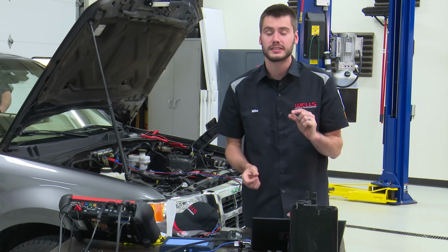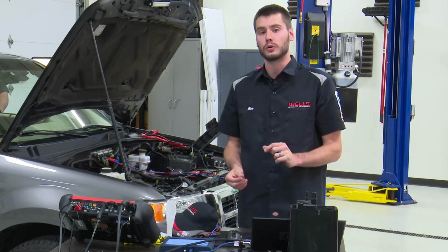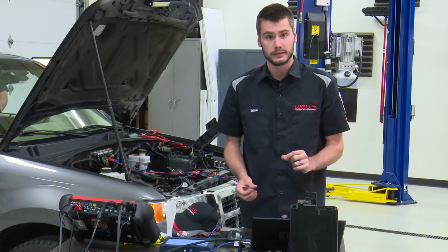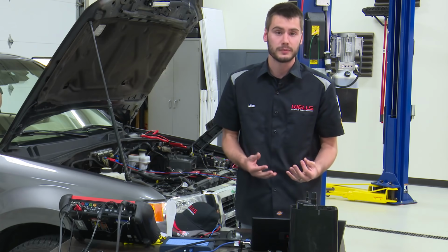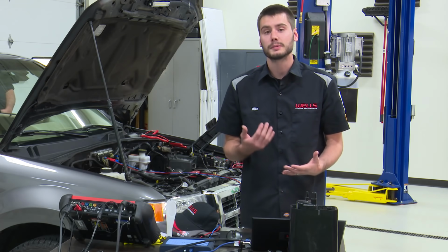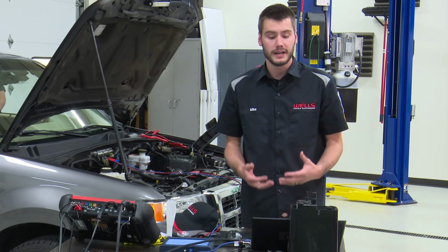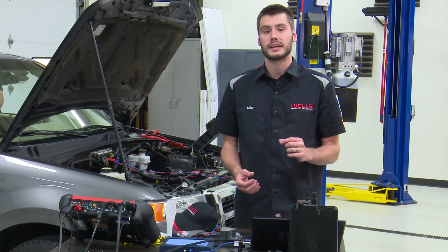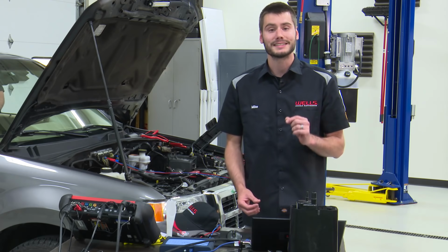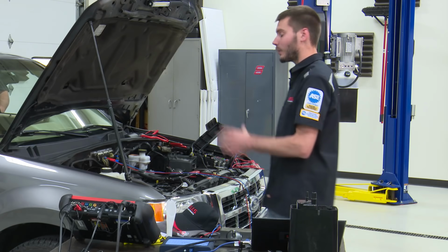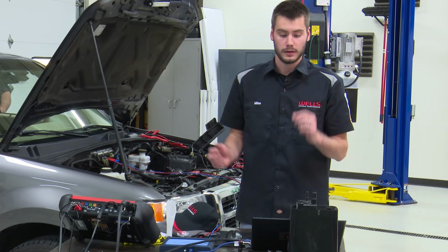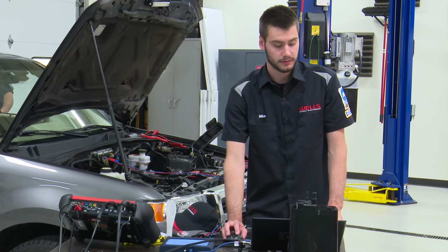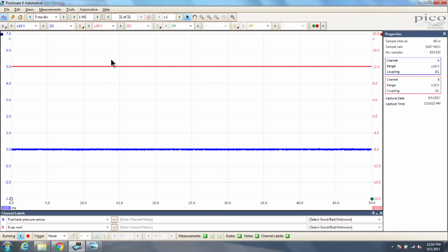That little processor inside of there, its job is to ground control the vent solenoid, right? Well, you can't ground side control something unless it's powered up, right? So we supply power to our vent solenoid at all times so that this little processor inside of there that takes very little current to run is able to turn on the vent without waking everything up by grounding this and having our vent solenoid turn on. So 12 volts right here on this vehicle is normal for key off, engine off, hot at all times.